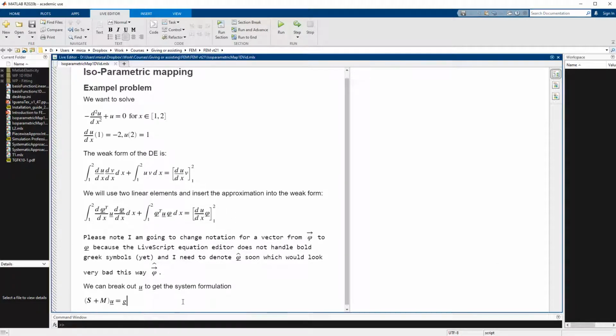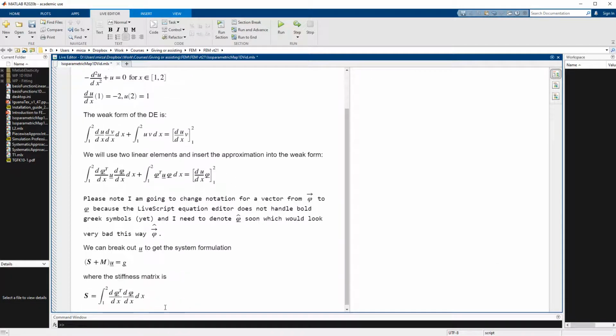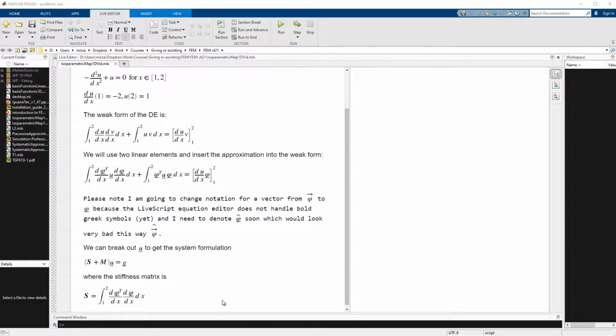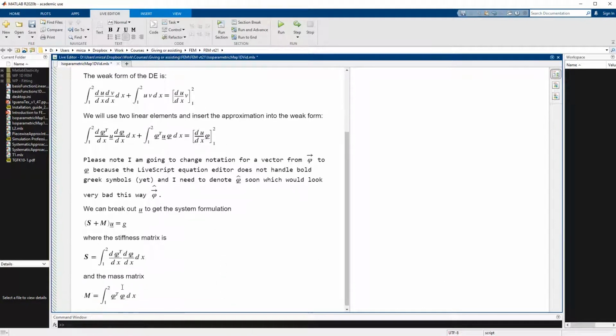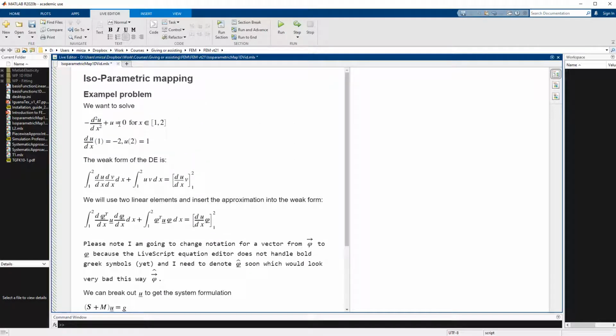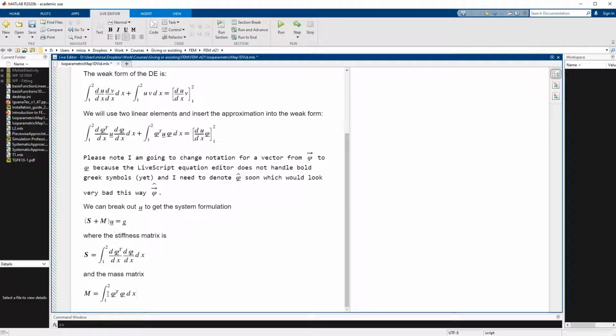We will have our stiffness matrix here, which we recognize from earlier, and we will have the mass matrix be this thing here. So wherever you see u, think mass matrix, because it will lead to that. Now I can go into why this is called the mass matrix. It comes from weighting density, and overall it will become the mass of an object.